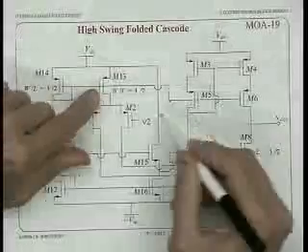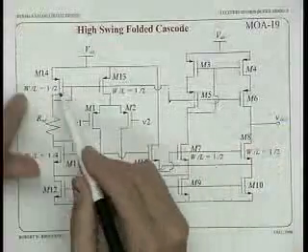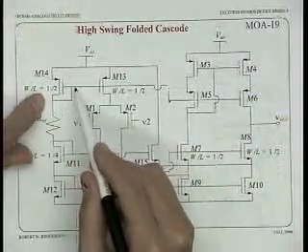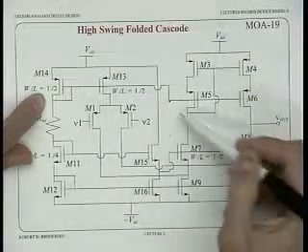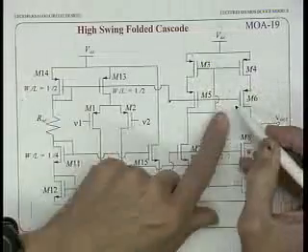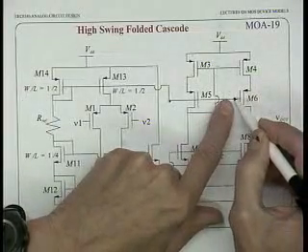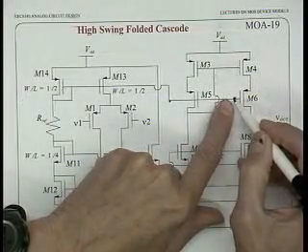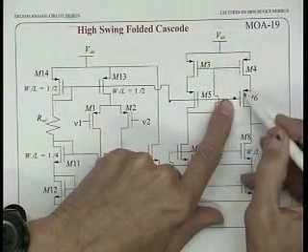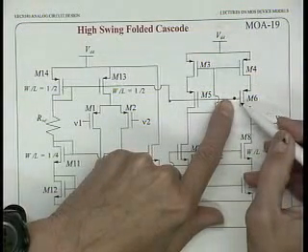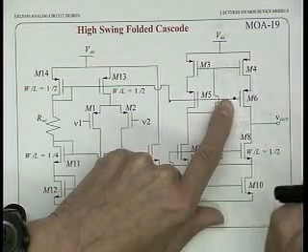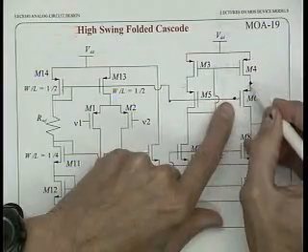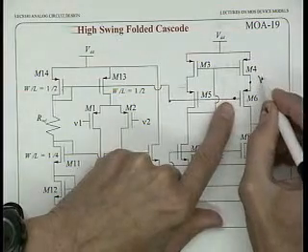All right. But look what's going on here. We're taking this bias voltage here, and so this is just a cascode. So this is just a strategy for biasing up the cascode. Here, good old standard strategy, we're taking that DC voltage, applying it to M6. So this is good old common gate sort of circuit, okay? So this is a cascode for M4, so that's just kind of normal. What we'd like to have is this voltage right here at what voltage?